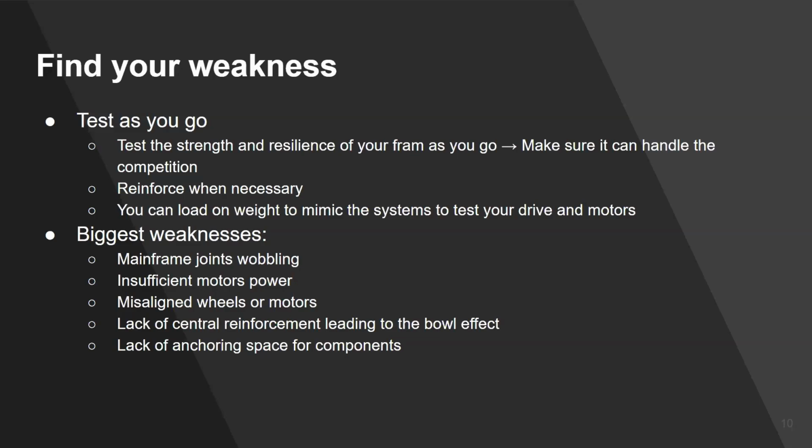One thing that we used to do is build our systems a little bit, kind of throw everything that we need for a system onto a scale, see how much it weighed, and then add weights to our drivetrain and see if it could go with it. At some point we knew we were going to have a very heavy robot, so we tried to see how many of our teammates we could put onto our drivetrain before it stopped being able to roll at the speed we wanted. So we would actually stand on our robot and test out the frame and the drive system that way.